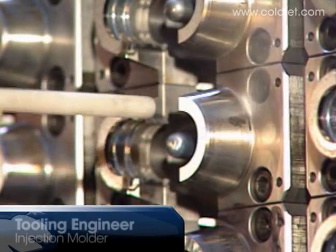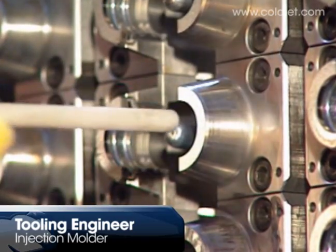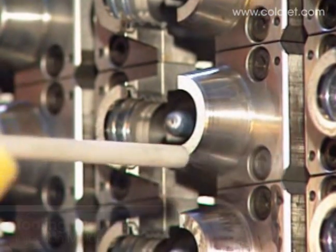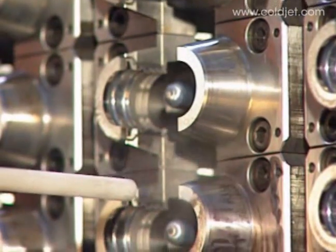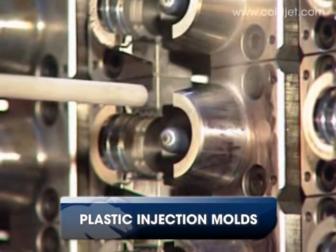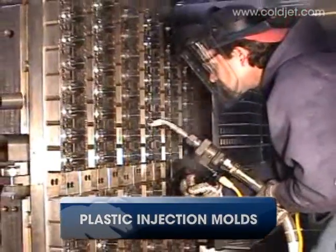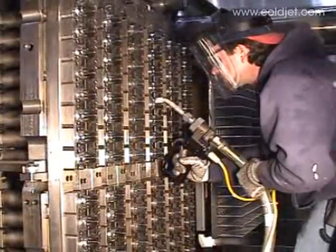Most of our molds are textured molds. The residue and buildup from the plastic starts to fill up the texture. And by keeping the molds clean and by keeping the residue out, we get a much sharper texture definition after the part is painted, which makes it a better looking part and in turn makes our customers happier.